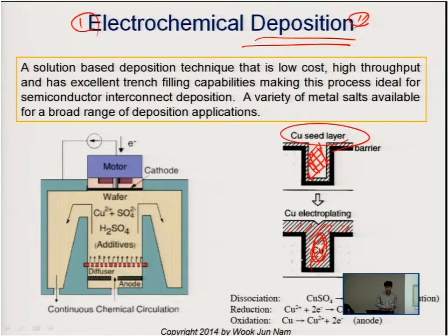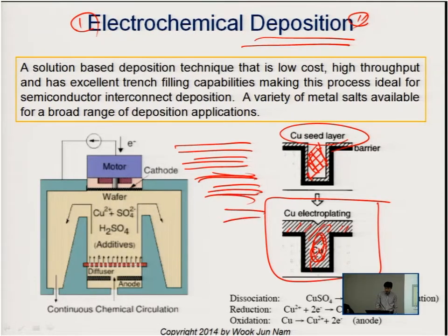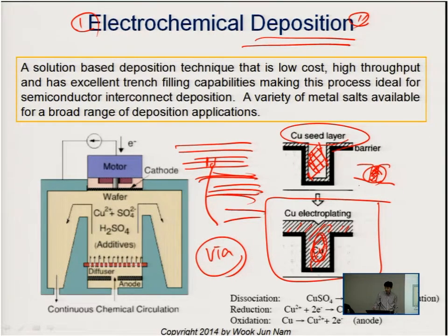That is why the industry making small microchips is interested in using this technology, because they have multiple layers of devices, and they use interconnects called vias, which are nothing but very small nano cavities. They fill this nano cavity with a metal layer so they can connect the transistor built underneath and the transistor built in the upper layer.